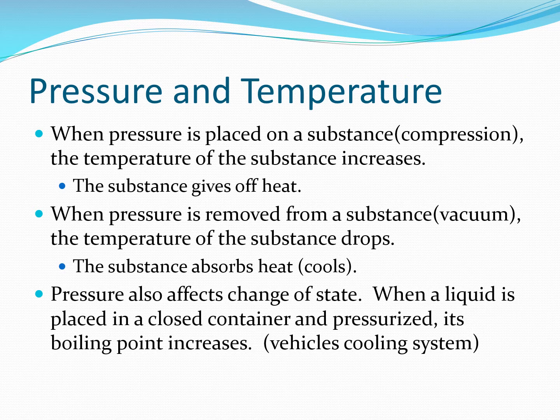But what's inside that can? Most of us, if we've dealt with a can of propane, can feel the propane sloshing around inside the can. We know it's in liquid form inside the can. Well, why is it liquid in the can and it comes out as a vapor? Well, it's under pressure. It's just like the cooling system on your automobile. If we put that liquid in that can under pressure, then it raises the boiling point and it becomes a liquid. But when you open up the valve and that liquid immediately hits atmospheric pressure, it's no longer under pressure. It reaches its boiling point immediately, and that's the vapor you see coming out.